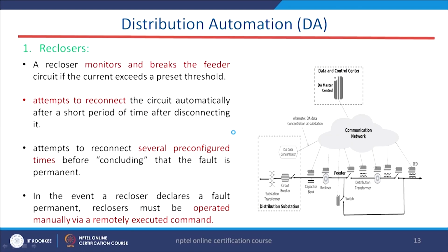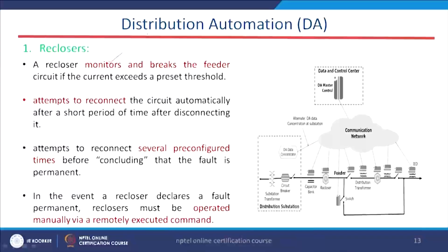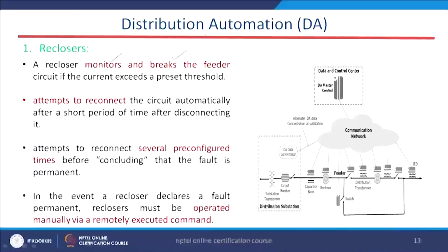Now, basically the recloser is one of the components of the smart grid system. And what is the function of it? Basically it monitors and breaks the feeder current if suddenly the current magnitude exceeds the set value or certain threshold value, or the predefined value.